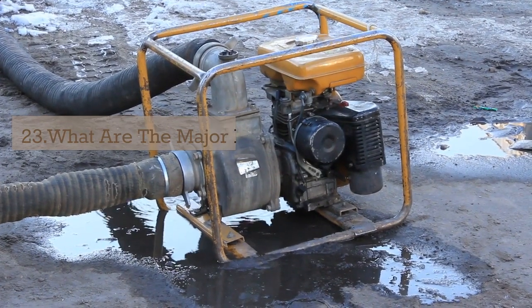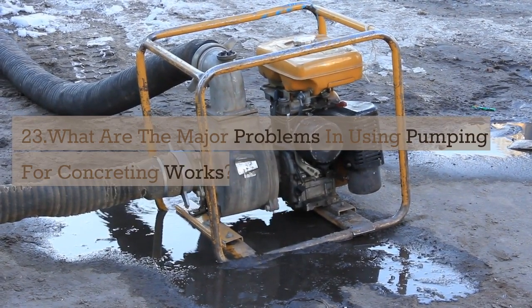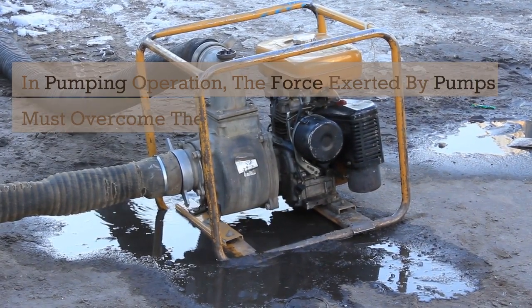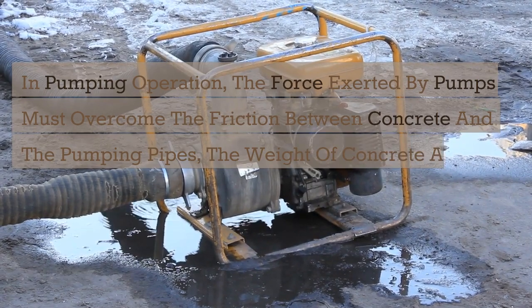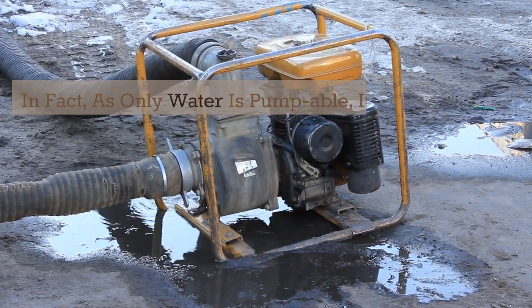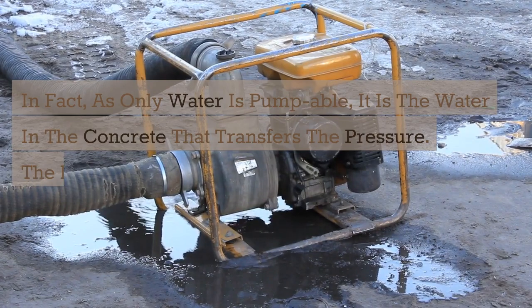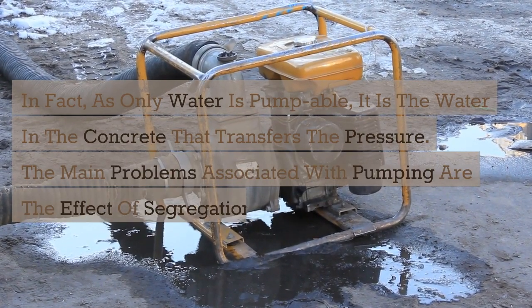23. What are the major problems in using pumping for concreting works? In pumping operation, the force exerted by pumps must overcome the friction between concrete and the pumping pipes, the weight of concrete and the pressure head when placing concrete above the pumps. In fact, as only water is pumpable, it is the water in the concrete that transfers the pressure. The main problems associated with pumping are the effect of segregation and bleeding.